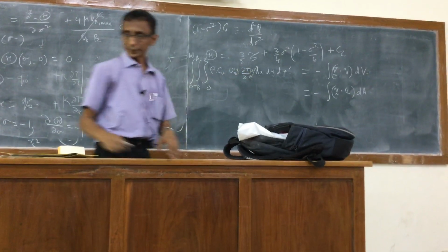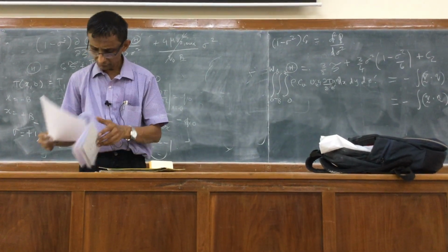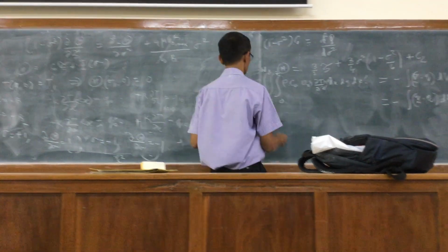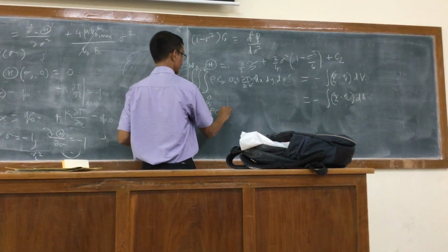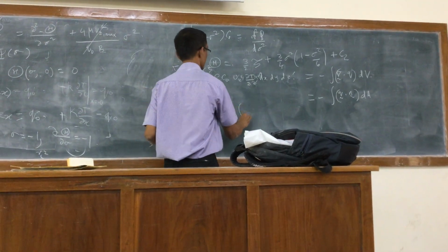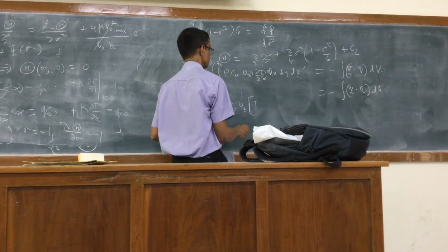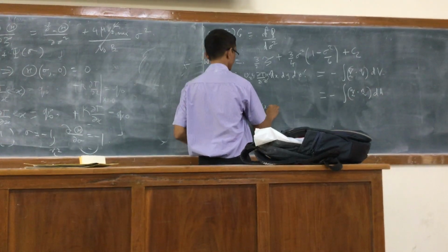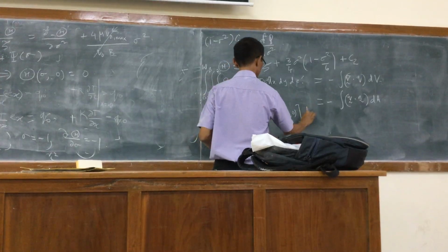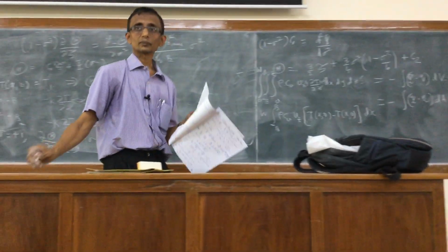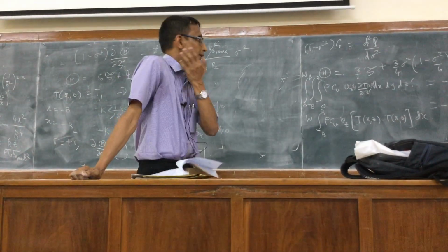So I can integrate that, and what I will get is W, integrated from minus b to b, rho cv dz times T of x, z minus T of x, 0, dx. The dT by dz prime will get integrated, and there will simply be a difference in the temperature.